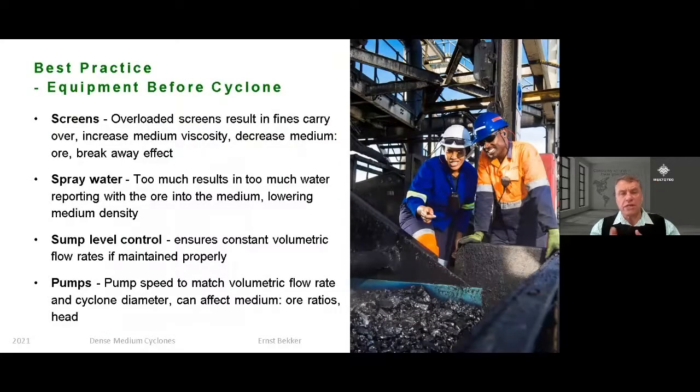The equipment before the cyclone, again, we've talked now in the overall process just now. So some of this is again some repetition, but it's deliberately done like this to drill this into the mind of the viewer. Your screens, if you overload your screens, the fines carry over. Something to keep in mind. That can increase the media viscosity.